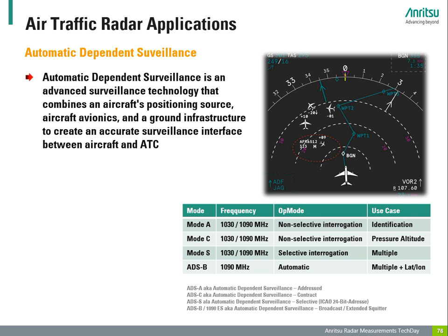It can also be transmitted and received point-to-point by other aircraft to provide situational awareness and allow self-separation. ADS-B is, in a sense, automatic in that it requires no pilot or external input. It is somewhat dependent in that it depends on data from the aircraft's navigation system. ADS is operated in different operation modes, called A, C, and S. We will use later a so-called Mode S signal for demonstration purposes.